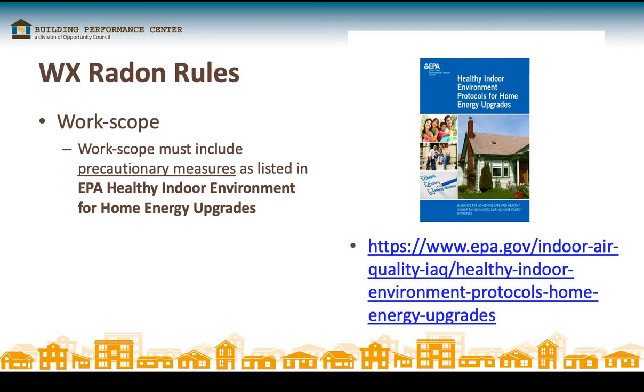It tells us to air seal sump pumps, installing airtight sump pump covers in such a way that water can drain from above and below the sump cover. They require us to install airtight drain fittings or traps in the foundation, if you have a floor drain, and seal and caulk penetrations, openings or cracks in below grade walls and floors that contact the ground with a sealant that meets the requirements of ASTM C920.